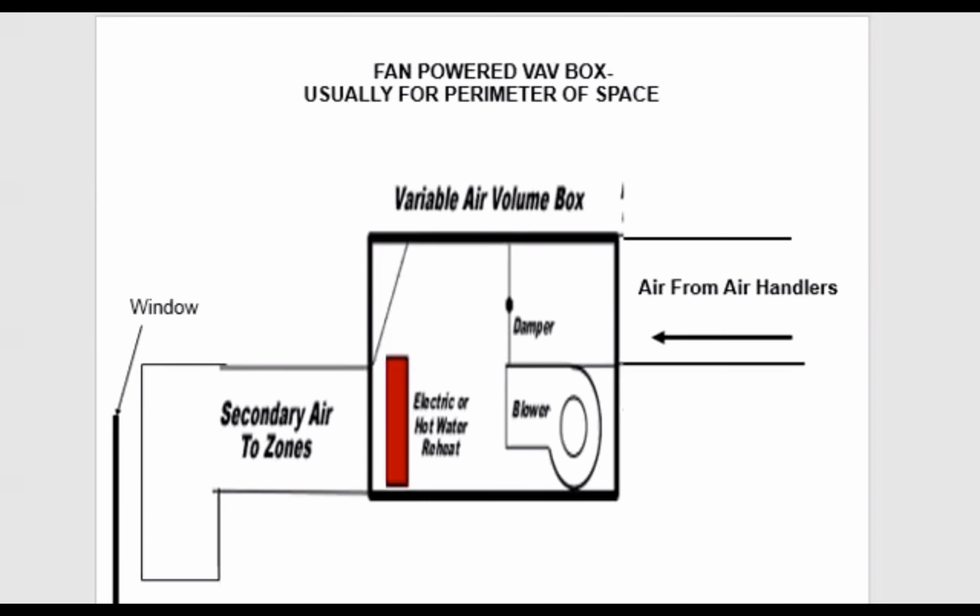All right. So again, the VAV depends on temperature settings. It will often have a secondary blower. In the long run, if the air from the air handling units has to travel a long way and it loses some of its velocity, then to keep air moving through the vents, there might be another blower along that run just to keep things moving along.